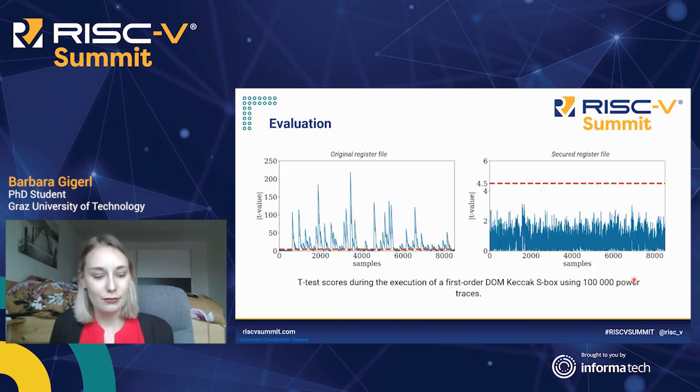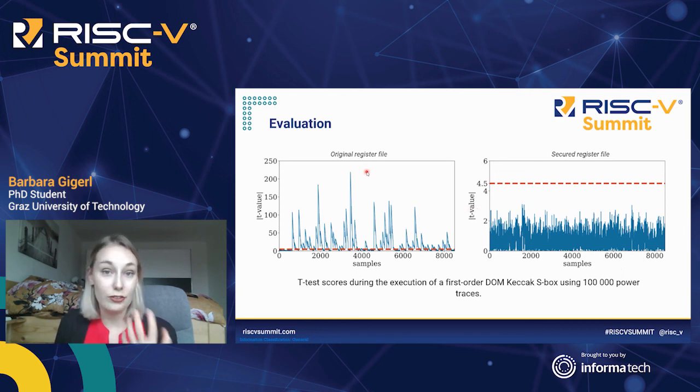Okay, so of course, we also did a practical evaluation of all of this. We put our design onto an FPGA board and did the evaluation. In this evaluation we compared the original register file without any security fixes to the secure register file with the gating. And we observed the power consumption of this register file while a first order DOM Keccak S-Box is executed.